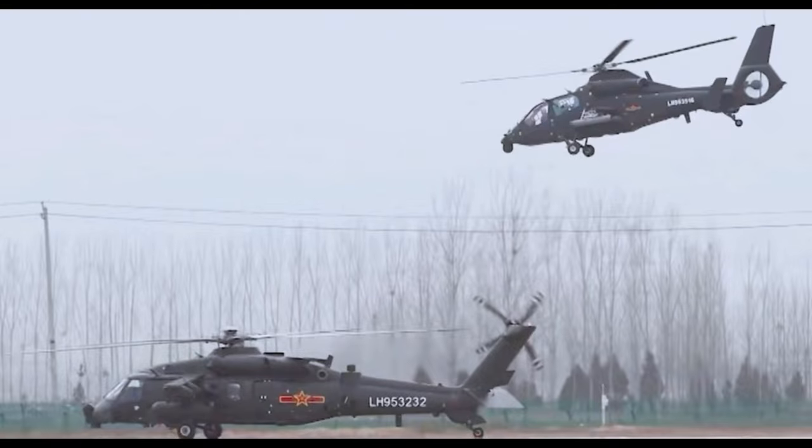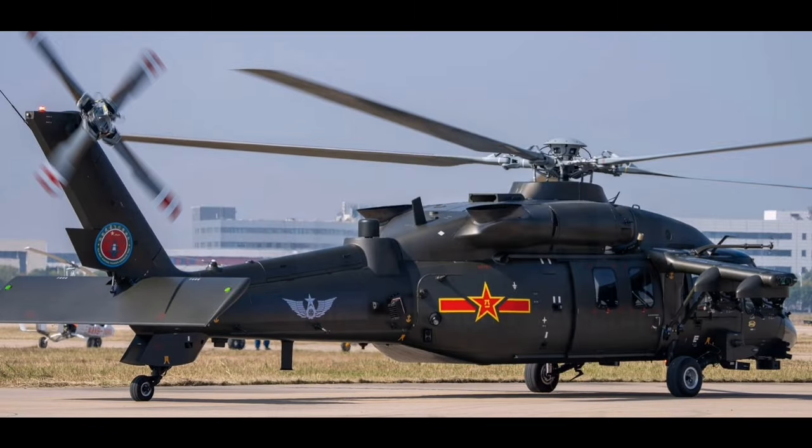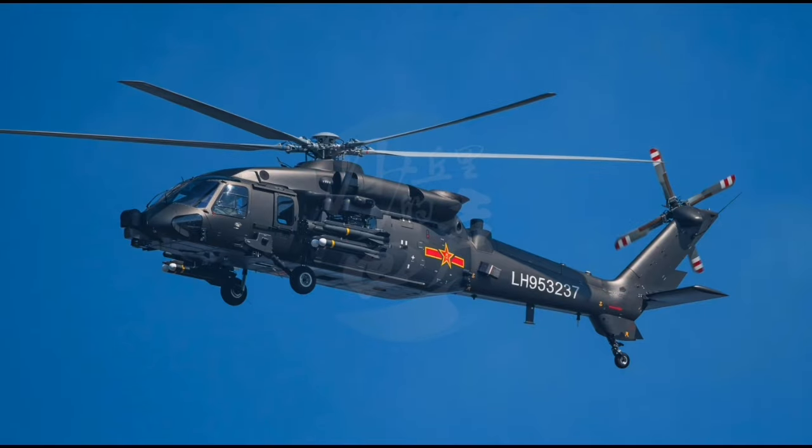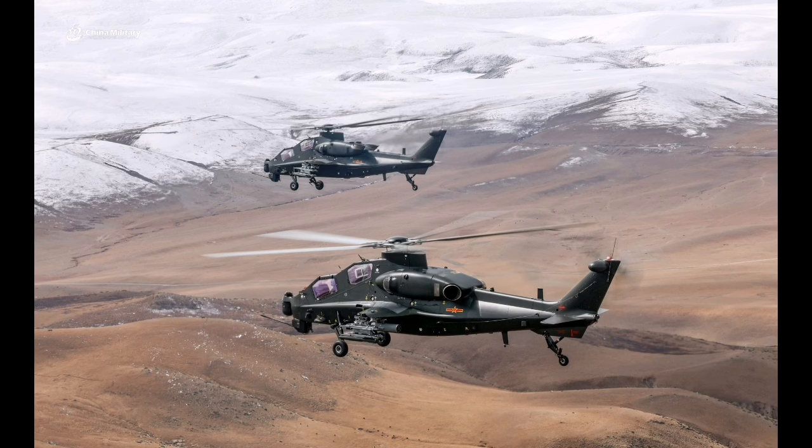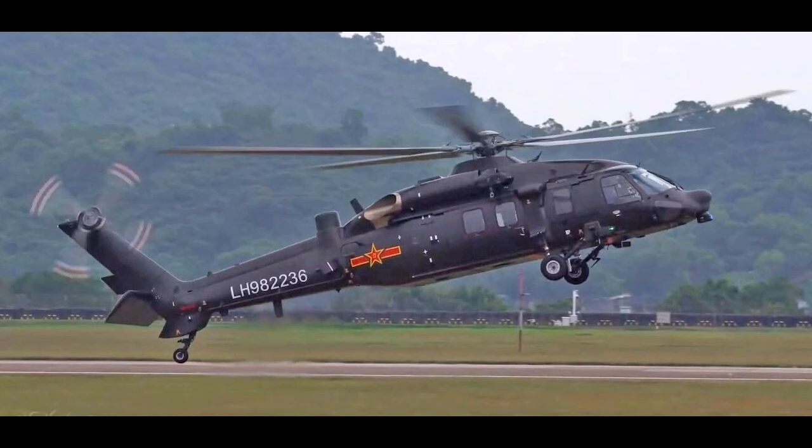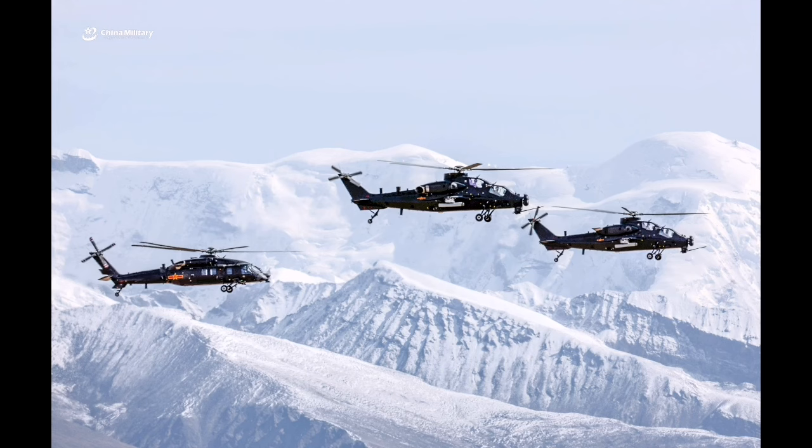To enhance its survivability in a contested environment, the helicopter is fitted with a defensive aids system. This integrated system typically comprises a radar warning receiver to detect when the aircraft is being illuminated by enemy fire control or acquisition radar, a laser warning receiver to alert the crew to laser designation, and a missile approach warner to detect incoming heat-seeking or radar-guided missiles.